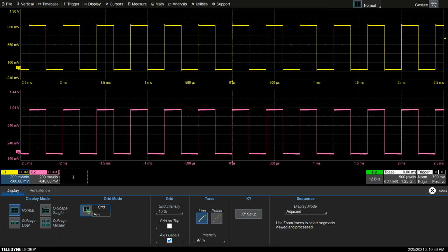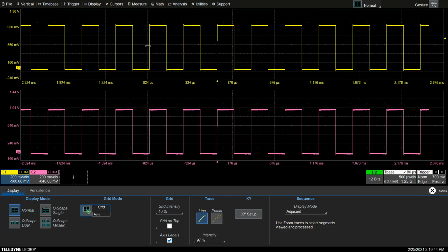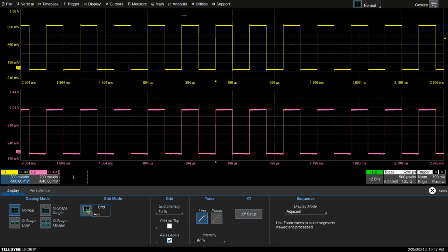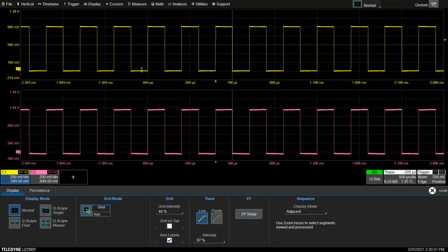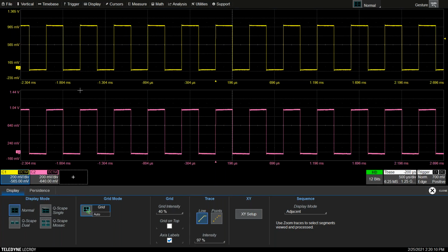One of the 3 ways to make measurements is to just use the waveform grid. Position the waveform, let's put it over here, we're running live again. And then we can say, okay, we know that each grid is that, and we're at 500 microseconds per division. We can make some really ballpark measurements. We can see that that's like 3/4 of a division, so 3/4 of that puts it at what, 350. That's not very accurate, but same thing with the amplitude, we can move it and change the offset so that we are on a grid, and therefore we're going to make measurements. So this is pretty much what you're used to doing. That's one of the 3 ways.